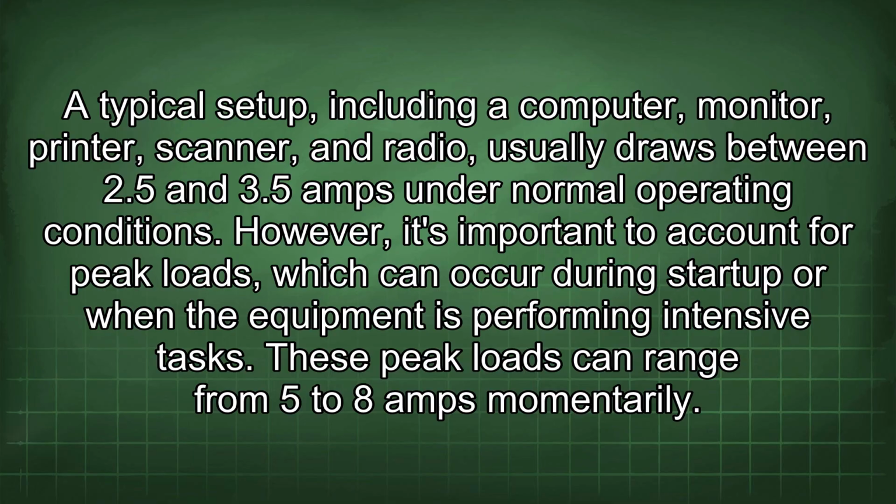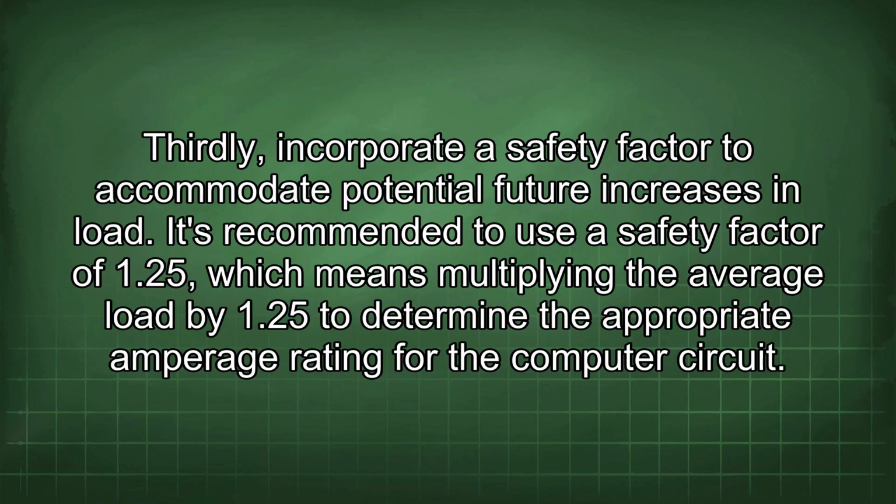operating conditions. However, it's important to account for peak loads, which can occur during startup or when the equipment is performing intensive tasks. These peak loads can range from 5 to 8 amps momentarily. Thirdly, incorporate a safety factor to accommodate potential future increases in load. It's recommended to use a safety factor of 1.25, which means multiplying the average load by 1.25 to determine the appropriate amperage rating for the computer circuit.